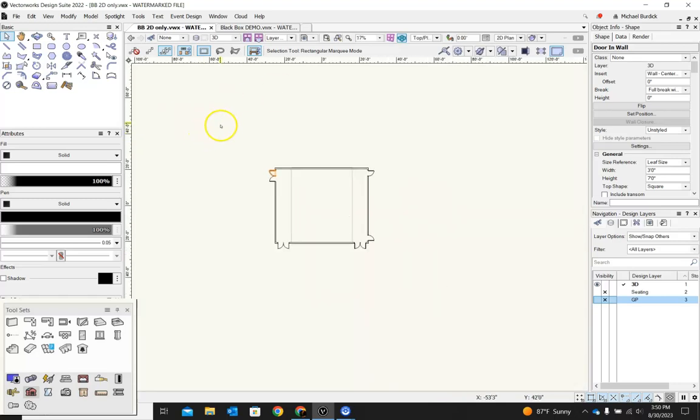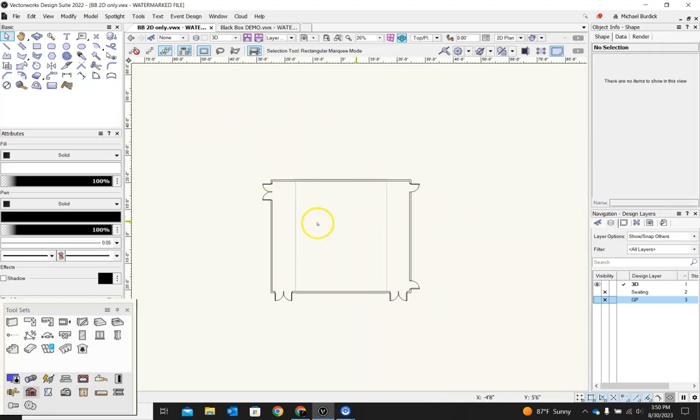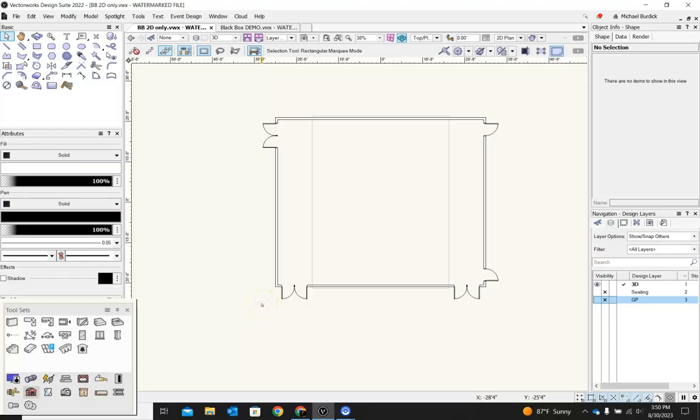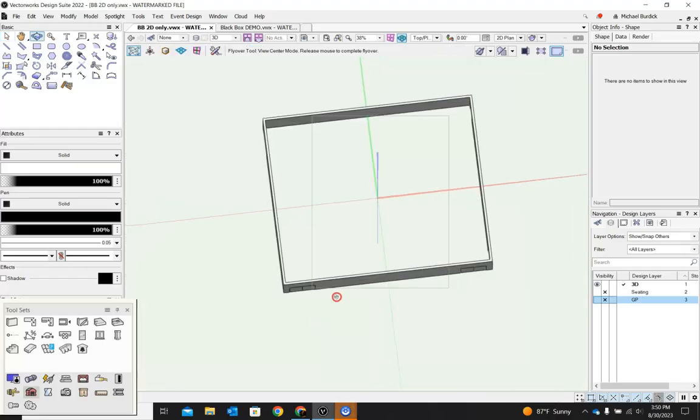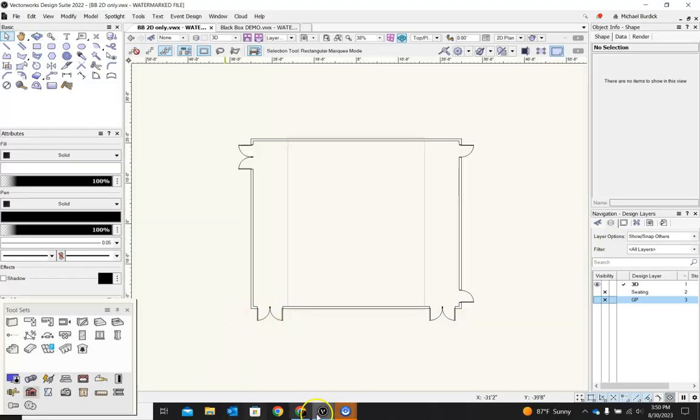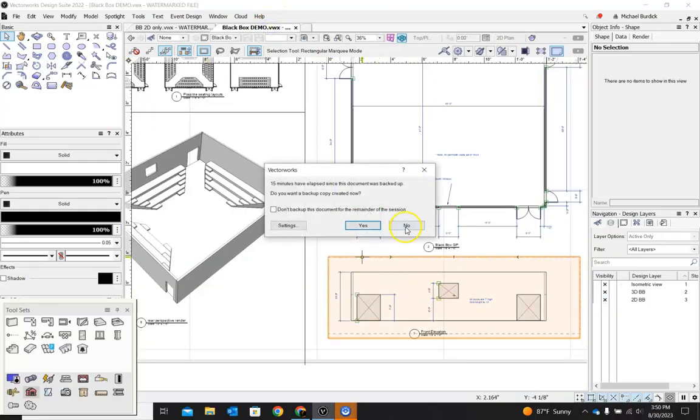So this actually, if you wanted to just build it in 3D and then look at it from a top plan view, that would give you a really nice looking ground plan. So that's an option. But just to know that when you're working in here with this building shell tool set, it's going to give you hybrid symbols that have one look if you're in top plan and another look if you're in 3D. Now, the only other thing we need to add is our little window here.